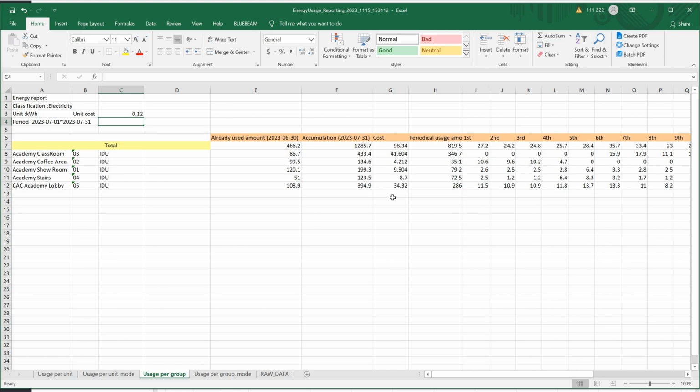Many countries have different prices for peak hours of the day, same as low demand hours, as well as different prices for holidays and weekends. Also, let me remind you, this energy we see is not the energy of the indoor units. These energy values represent electricity consumption of the outdoor unit, which is shared between indoor units based on their capacity, operation time, and mode. Simply speaking, it's all about fairly sharing the outdoor unit electrical bill between the indoor unit users.